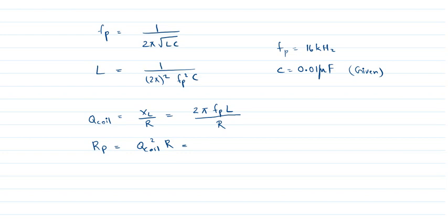I will give the value for R, the internal resistance, as 30 ohm, and you can take some approximation for the value. If it's not exactly 10 millihenry, say when you calculate it comes to 9.9 millihenry, you can approximate the value to 10 millihenry. Always the inductor's value will be like this. So you can find out the Rp also.